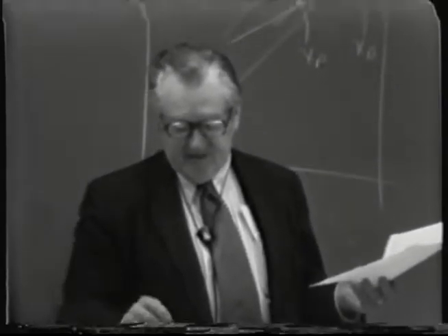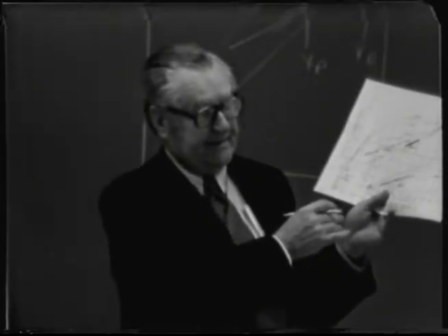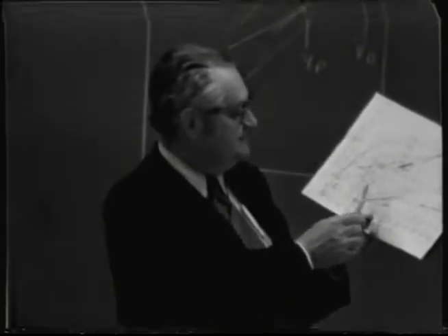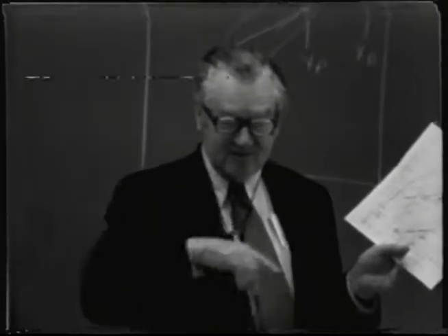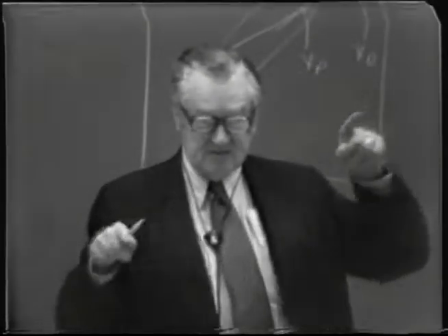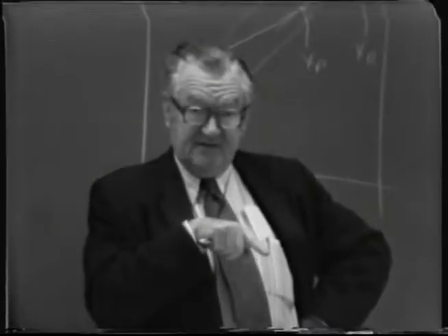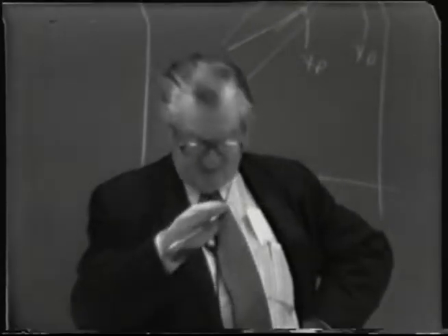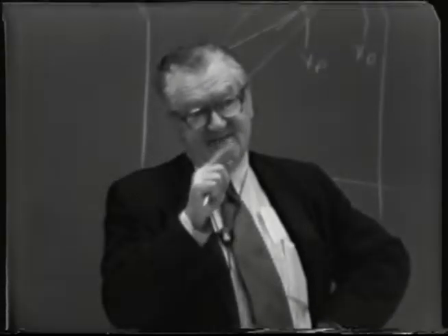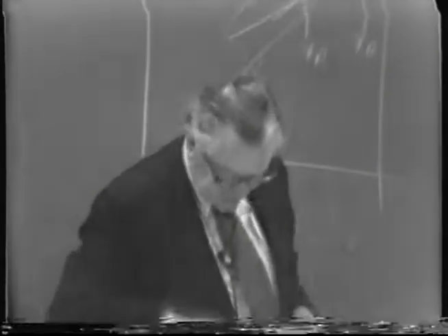I didn't bring it in with me, but I did solve this same part of the problem by replotting on what we call probability paper, logarithmic paper on both scales. I'll bring you an example of that when I get a chance. You plot the operating line and the equilibrium curve. In that case, the equilibrium curve down the lower end becomes a straight line, and the operating line becomes a slight curve. But at least it gives you a lot of space to work, so you can do it more accurately.